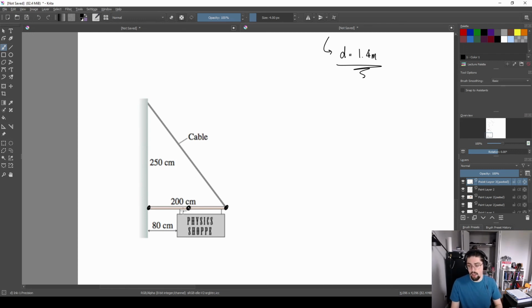So here's the kind of situation, right? Let me draw some of the forces that I know on this thing so far. Let's do that. I would say, okay, well, the 200 centimeter long pole actually has some mass, right? As annoying as that might be. So I'm going to say, all right, well, there's a mass of the pole, mp times g. Gravity pulls on that. There is the mass of the sign pulling over here like this, call it ms times g. And then there's this cable attaching these things, so I'm going to expect to see a force right here as well. Call it t.